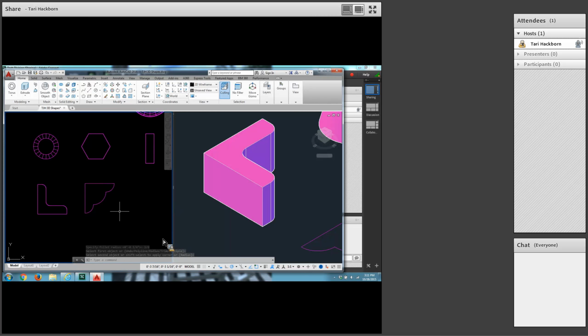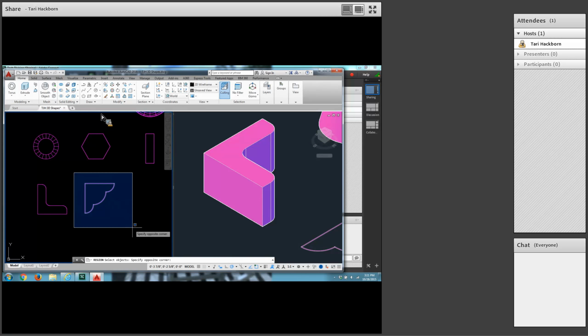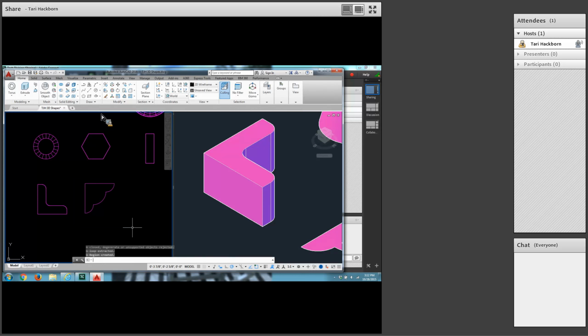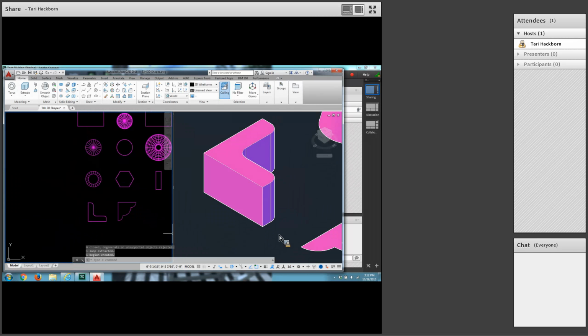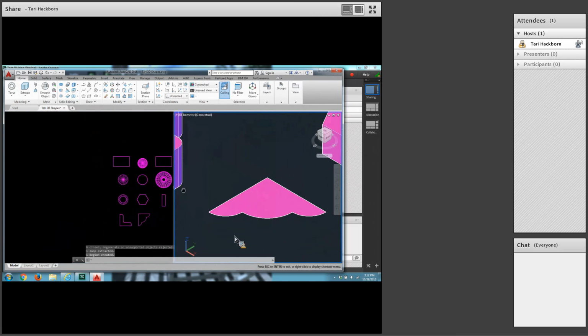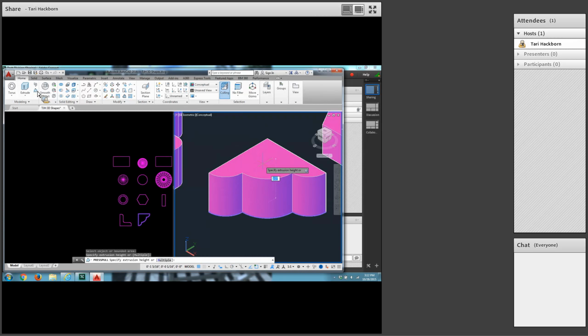Okay, now the same thing you did with the angle. I want you to change this into a region. This is where I'm always going to differ with the textbook. Region, it's easy. Draw region. Just select 2 corners of a window, and then enter. And then click over in this ISO view here. You can see it has surface. This time I'll do press pull. Click in the middle, pull upward, and type a 1/2 inch. Good time to do a quick save again.